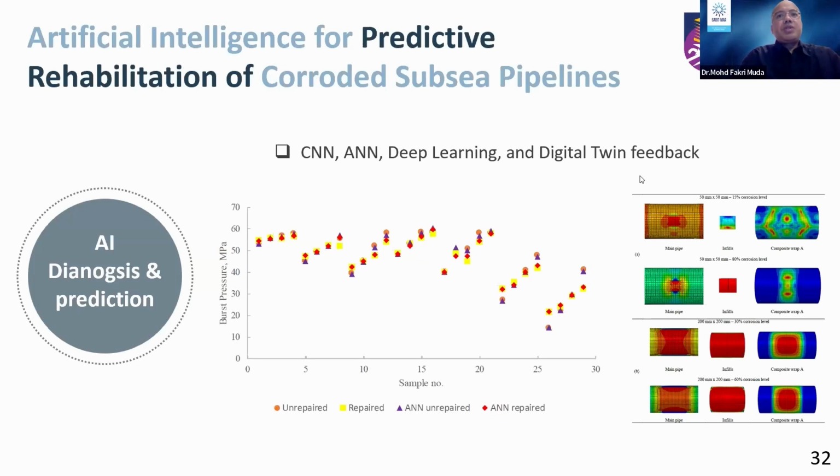According to some related research, such a hybrid framework achieves prediction accuracy of 90% and above for corrosion classification and less than 10% error in estimating the degradation rates. So the output of the predictive analysis directly informs rehabilitation planning. From that, we can determine when an FRP overwrap should be reapplied and how thick it should be, and where stress concentration may trigger secondary corrosion.